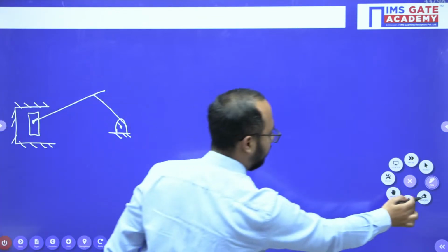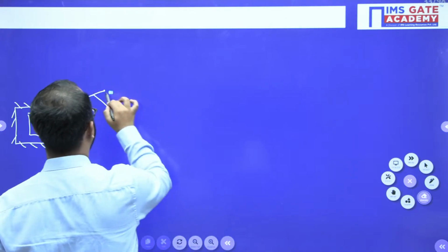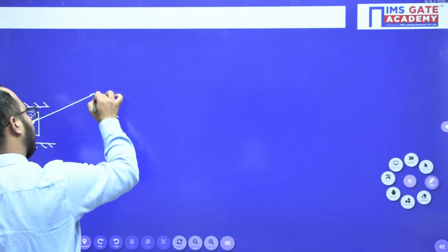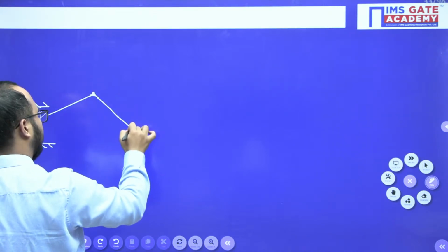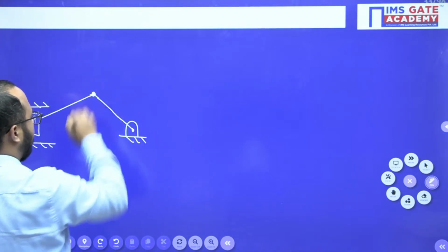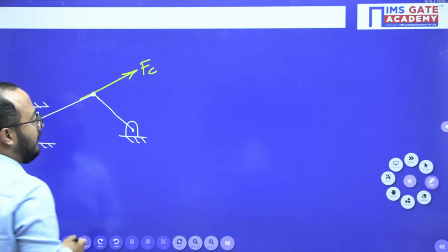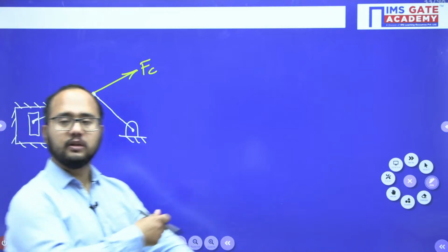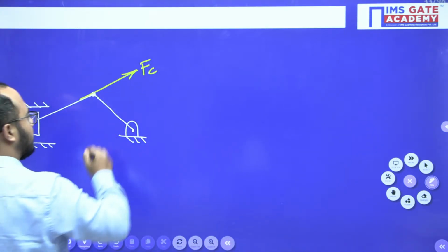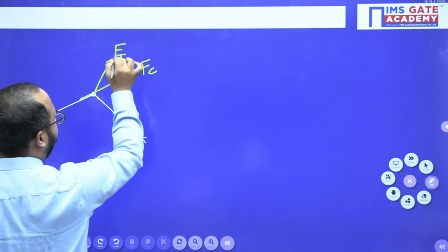Okay, now it is like this. Now see. Okay, now see. So along this connecting rod, this Fc force will be there, right? But this is a crank. Perpendicular force to the crank we have to calculate, so that we can calculate the torque, right? That is the point you should understand. Perpendicular to the crank will be known as the Ft, the crank effort, right?